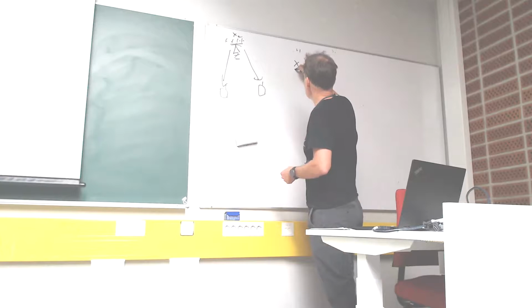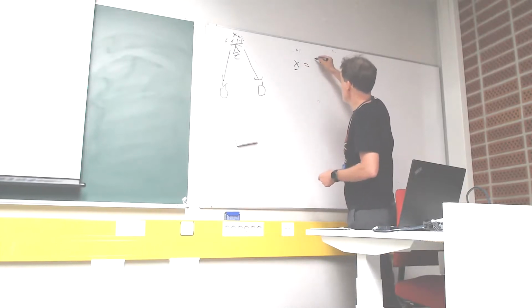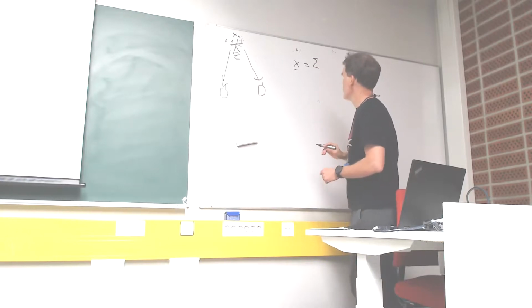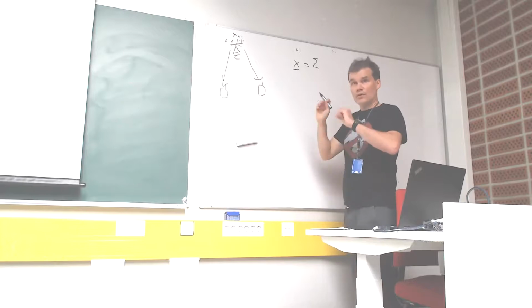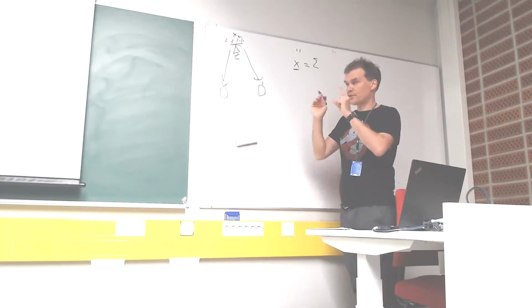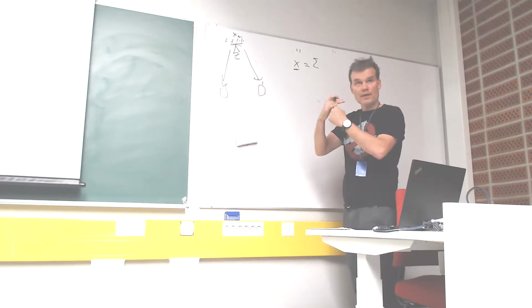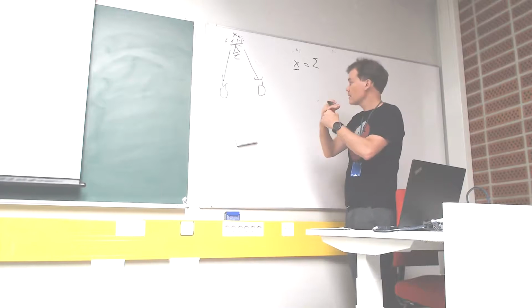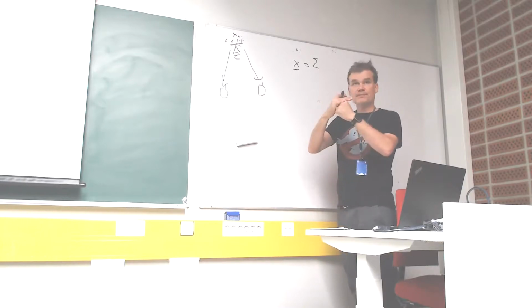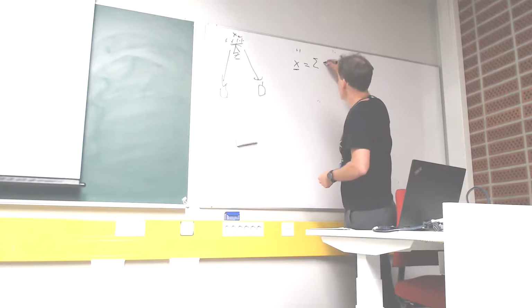So the transmitted signal vector is a superposition. Now we superimpose all transmissions, or all data streams, to K users on top of each other. And the separation happens via the precoders that we assign for each user.